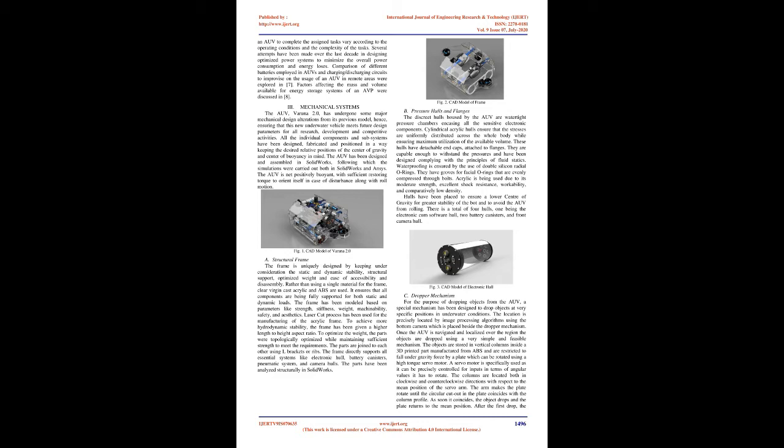The frame has been modeled based on parameters like strength, stiffness, weight, machinability, safety, and aesthetics. Laser cut process has been used for the manufacturing of the acrylic frame. To achieve more hydrodynamic stability, the frame has been given a higher length to height aspect ratio. To optimize the weight, the parts were topologically optimized while maintaining sufficient strength to meet the requirements.